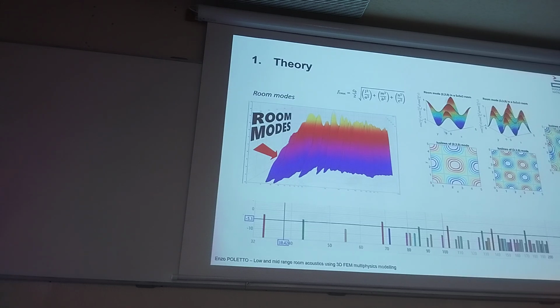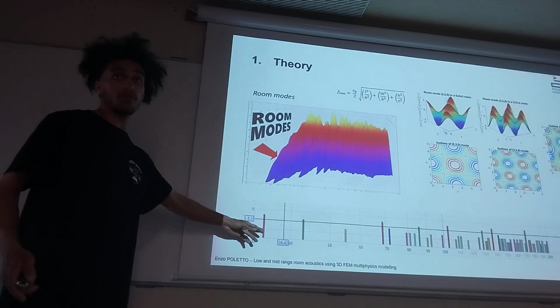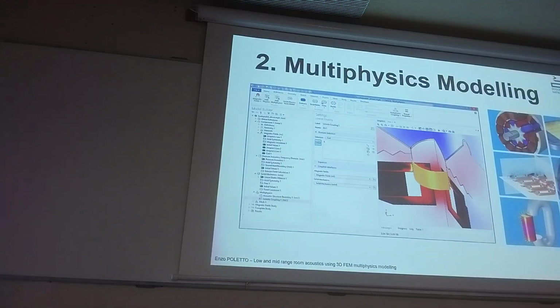I can also see that as the reverberation time: when I have a room mode, the frequency of interest is reverberating much more than the rest. And these are discrete modes. I can either calculate them if I have a simple geometry, like a rectangular shaped room, or I have to compute that in a 3D model to find all those room modes, and that's where our resonators come in. We're going to tweak them at those frequencies, basically, to make it simple.